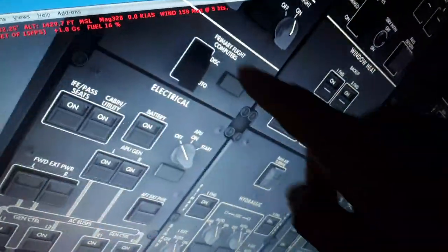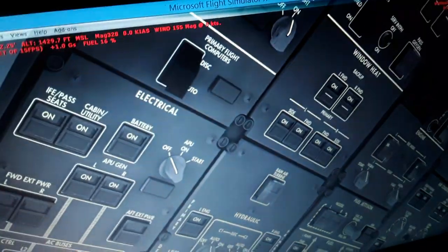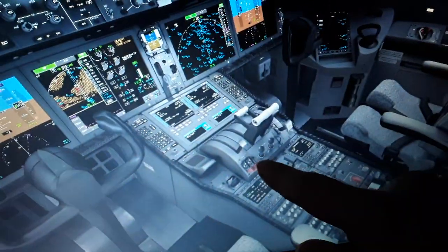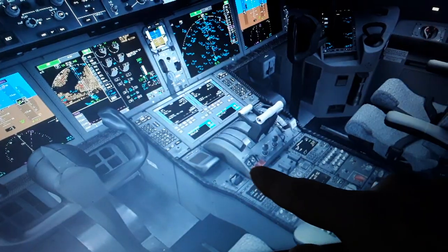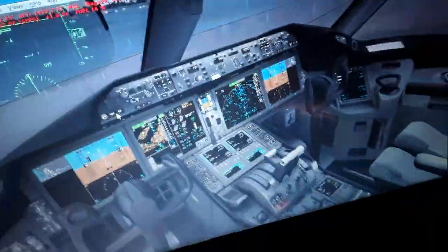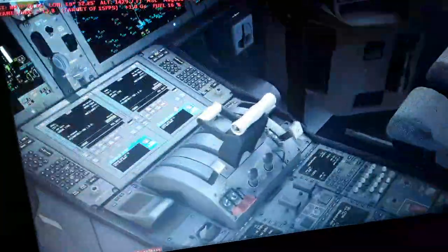We have the flight control computers also here. You can see primary flight control computers. It will affect, you disconnect from normal to cut off, you open the guarded switch and use only the manual trim over here. So you have also a couple more things to see.